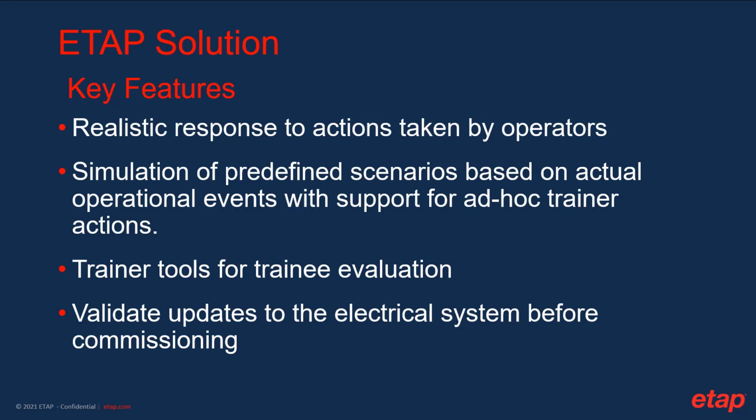Additionally, this can be used to validate updates to the electrical system before commissioning. So if you're bringing on a large addition to the electrical network, you can validate that using the OTS and make sure that both the system can handle this, as well as the operators are ready to hit the ground running once this equipment is commissioned.